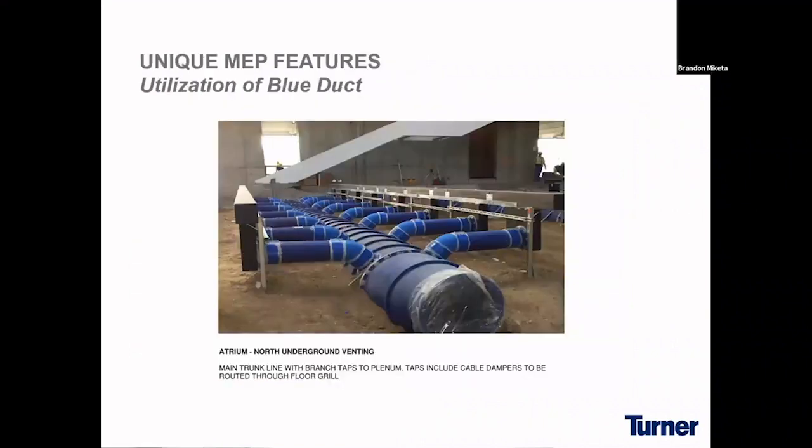Great, thank you, Russ. So continuing discussions on quality that Jeff and Russ had previously mentioned, I'm going to go into some detail in regards to unique MEP features within the building, as well as BIM, which is Building Information Modeling, and prefabrication. So BIM and prefabrication work hand in hand and are key factors to handing over a quality building to the owner. From a quality perspective, the largest benefit of BIM is being able to work through clashes before material shows up on site through your model.